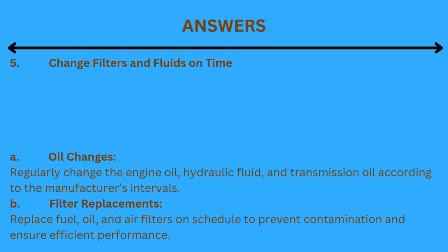5. Change filters and fluids on time. A. Oil changes. Regularly change the engine oil, hydraulic fluid, and transmission oil according to the manufacturer's intervals. B. Filter replacements. Replace fuel, oil, and air filters on schedule to prevent contamination and ensure efficient performance.